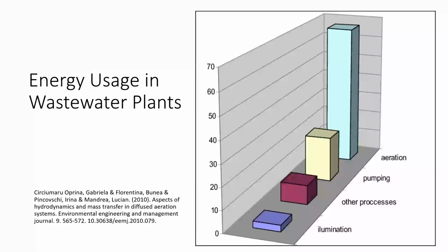I wanted to repeat this, put these 2 slides in that Nick had up last week because we didn't record this part of it. But I thought it was really interesting and very important. Typos notwithstanding in the graph there. The vast majority of electrical use in a wastewater treatment plant, an activated sludge treatment plant, is aeration, that big blue bar over there, somewhere between 60 and 70%, over half of the electrical use. And very interestingly, to dial in nitrogen and phosphorus more often than not, and I would say the vast majority of the time, ends up with less electrical use. So not only are we talking opportunities for improving nitrogen and phosphorus, we're talking about opportunities for reducing electrical use.